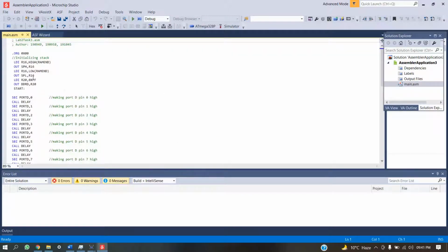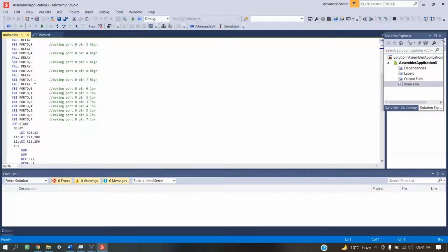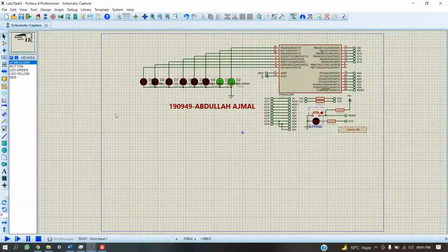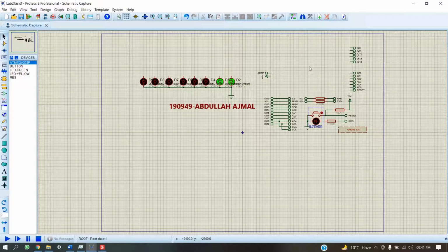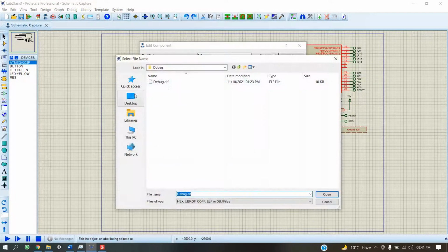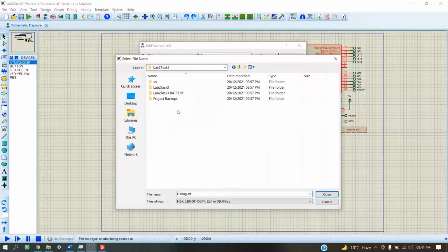Basically we are declaring our port D as our output port and then displaying values one by one, making one LED high, and at the end we are making all the pins 0. This is a loop for a 1 second delay, using a delay function by calculation, which will waste our cycles for that delay. So now let us simulate, add the file, task 3, and then simulate.